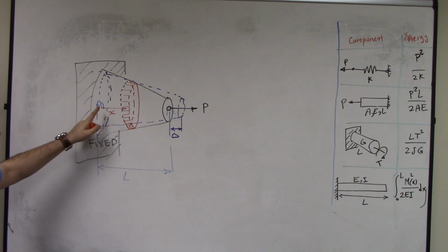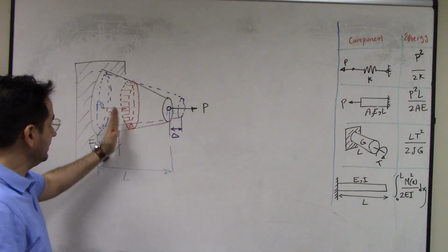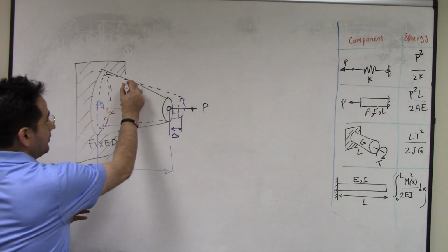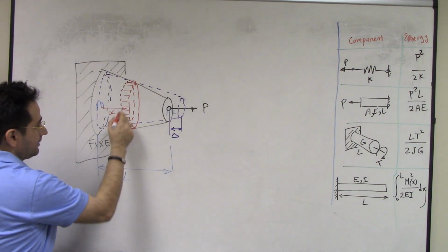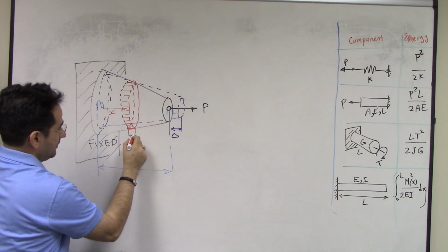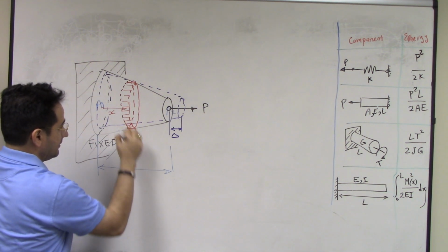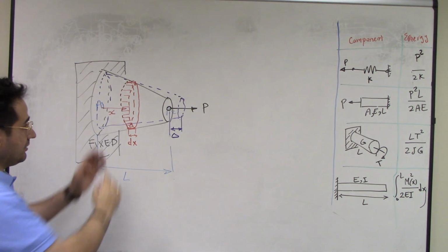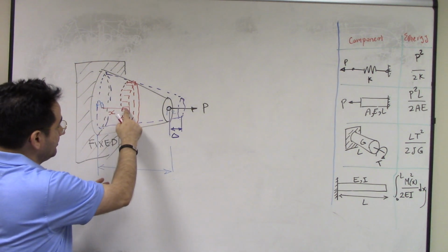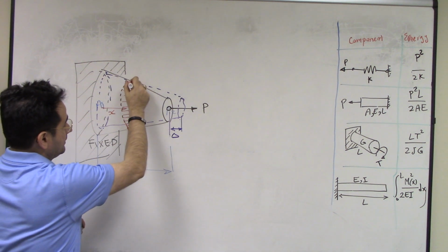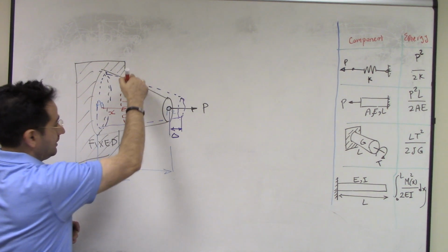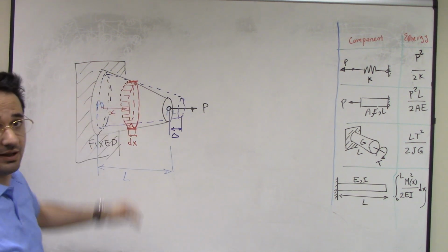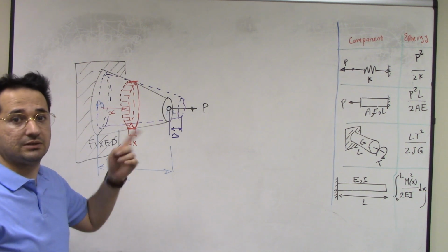Let's say we have an x coordinate starting at the bottom. So here x0, here xl. And then we consider just one infinitesimal tiny slice. If that's x, the length of this bar is dx, infinitesimal. And because this is infinitesimal, we can approximate this curvature as just constant, exactly like the Riemann series we did in integration.